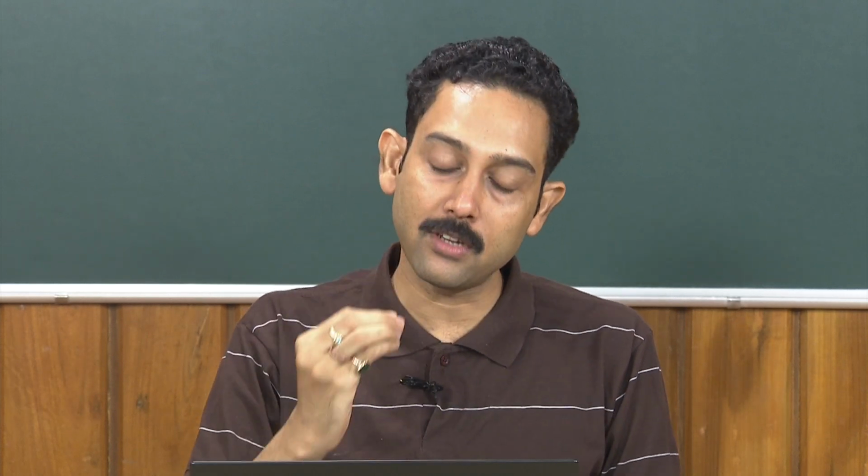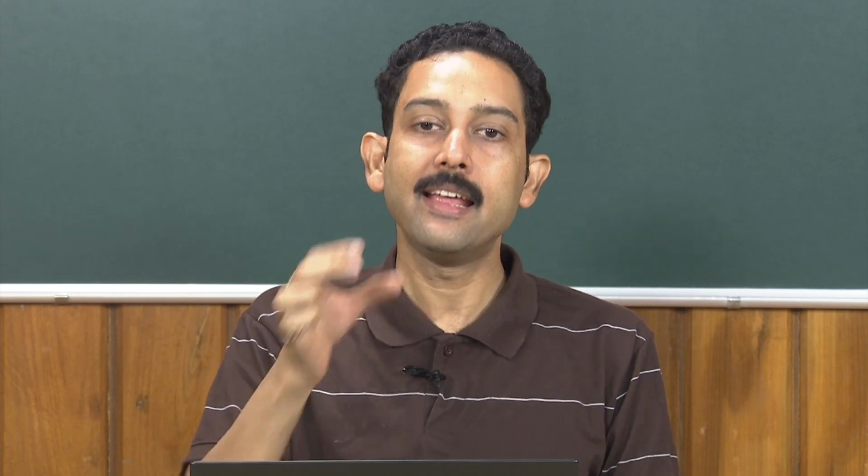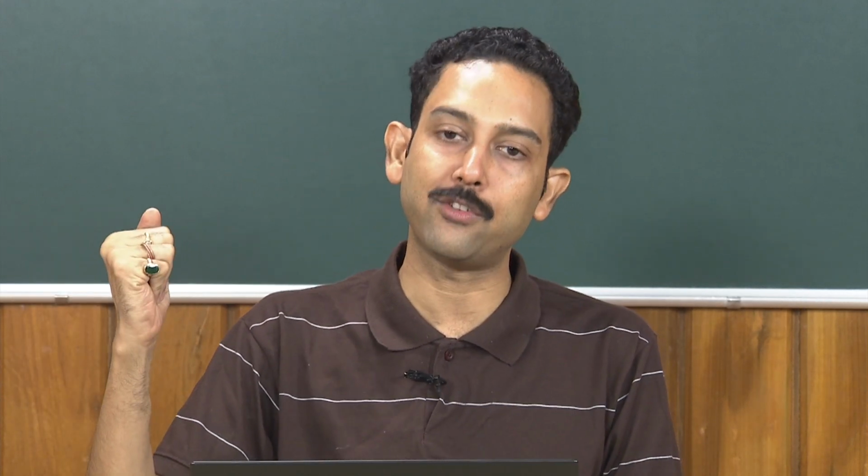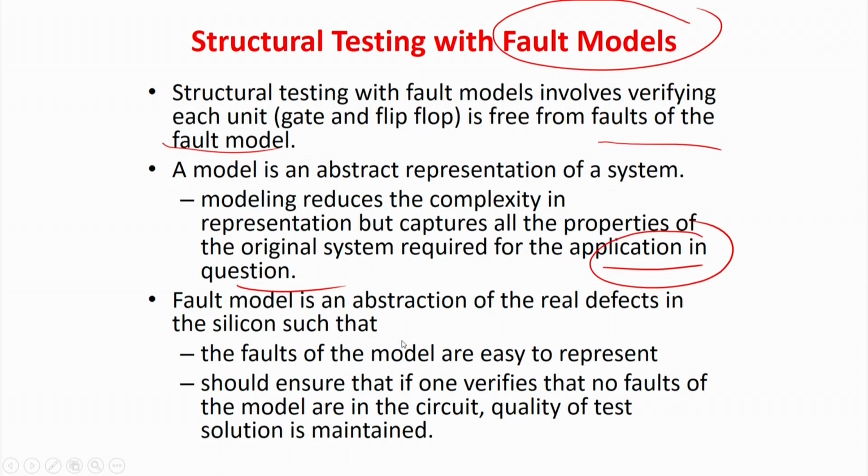So, fault modeling was the key buzzword, and it has solved most of the problems in testing. People have statistically found out that you need not test the functionality of the gates even. Rather, you try to find a good quality fault model which the gates mostly suffer from, and try to verify that such faults do not exist in the gates at all. If you establish that by testing, then there is 99.98 or 99.99% assurance that you are not selling a bad chip to a customer, telling them it has no defects. That is, your binning is proper.